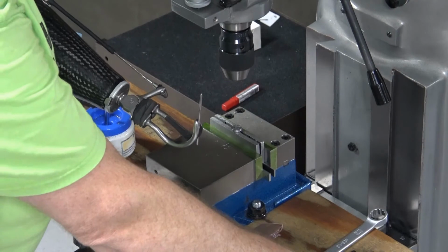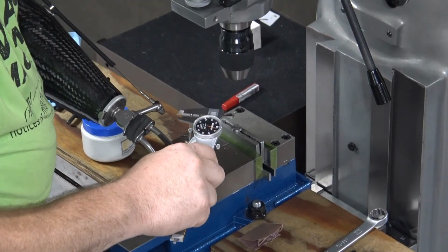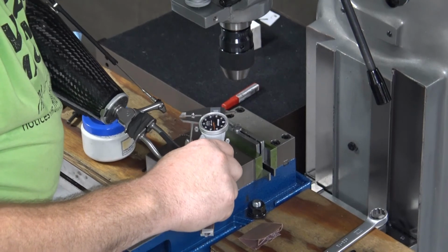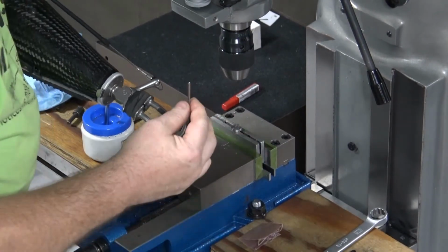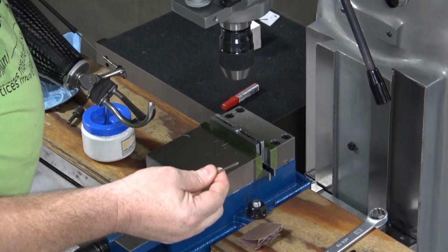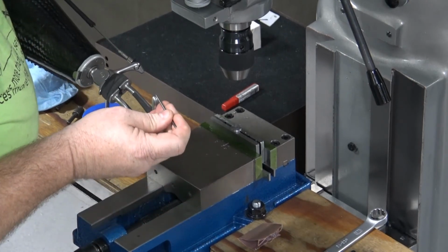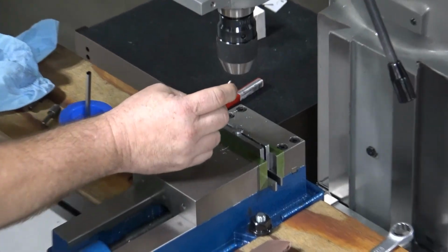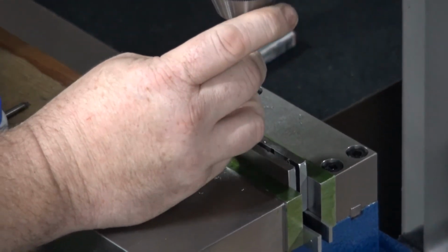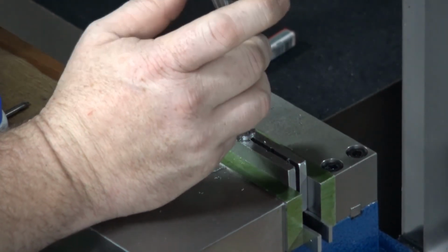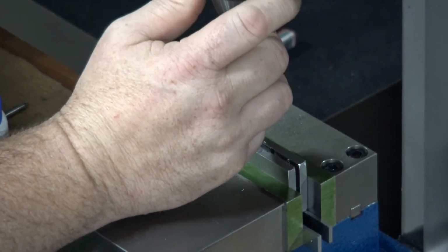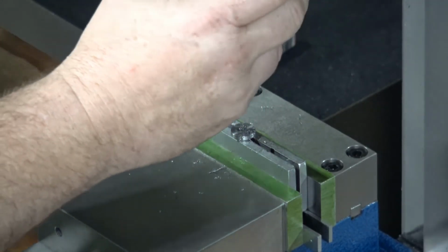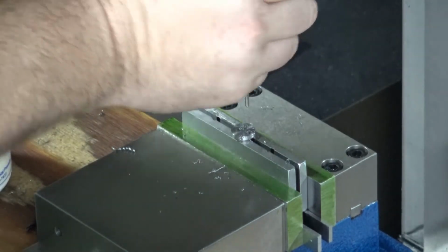Now we're back to a 4-fluted reamer. I'm reading 124, so this is the right size reamer. You see the value in us double checking that measurement. We can also look at the outside diameter, but you'll find out as you get a little bit older like I am, it's tougher to read those numbers. Okay? I'm going to grab that reamer.